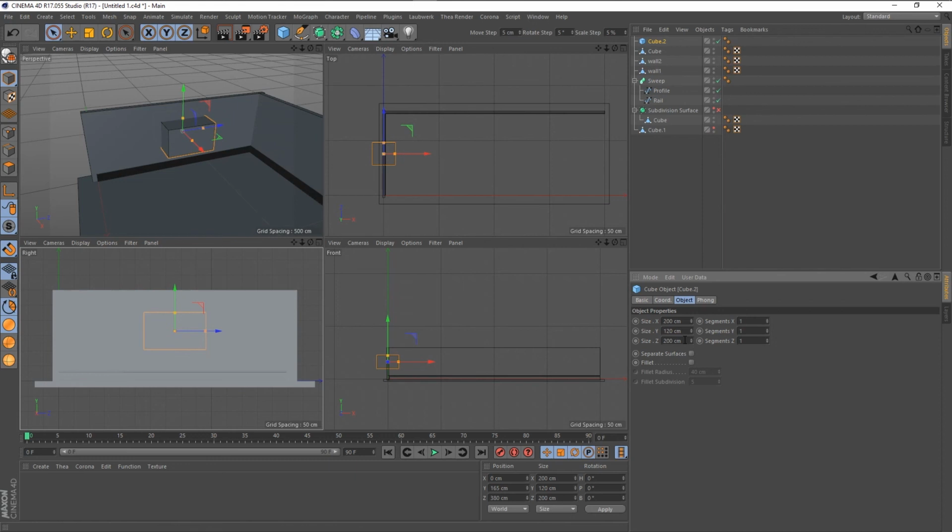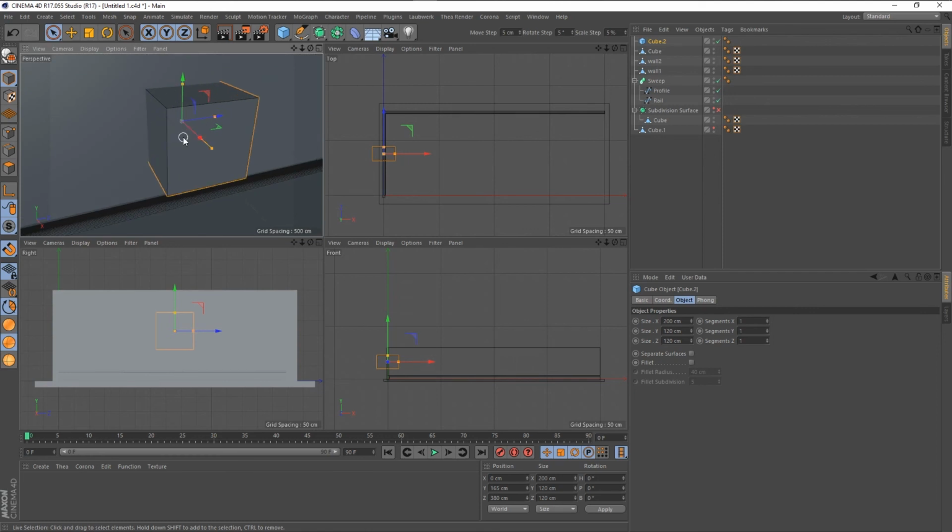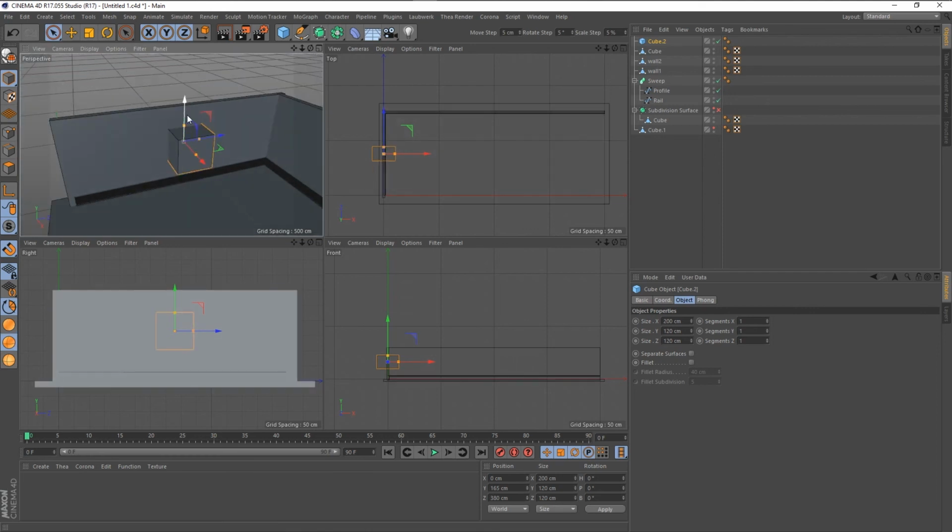And remember that in Blender, the up and down is actually in the Y and not in the Z. And then you have to figure out X is red and Z is blue. So in the Z direction, we also want this to be 120 because we want a square window, let's say 120 by 120. That's a typical European decent sized window, big window.